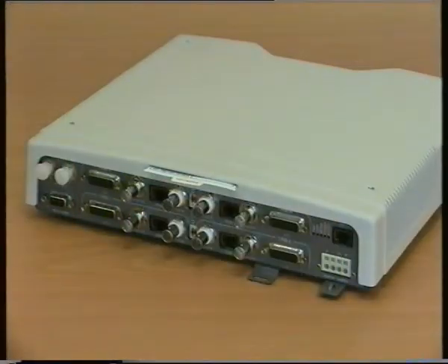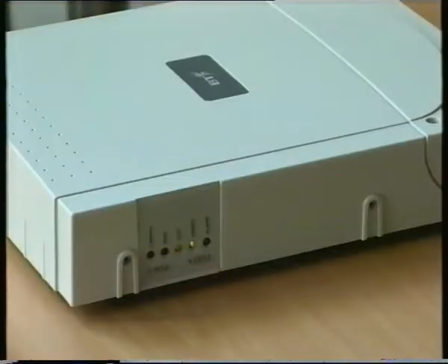Currently, the majority of wideband services, such as Megastream, are transported from BT serving exchanges to customer sites using fibre and copper systems based on PDH technology. Over the years, several systems have been used, the most recent being known as DWSS, that's Digital Wideband Serving Section, and CWSS, Copper Wideband Serving Section.